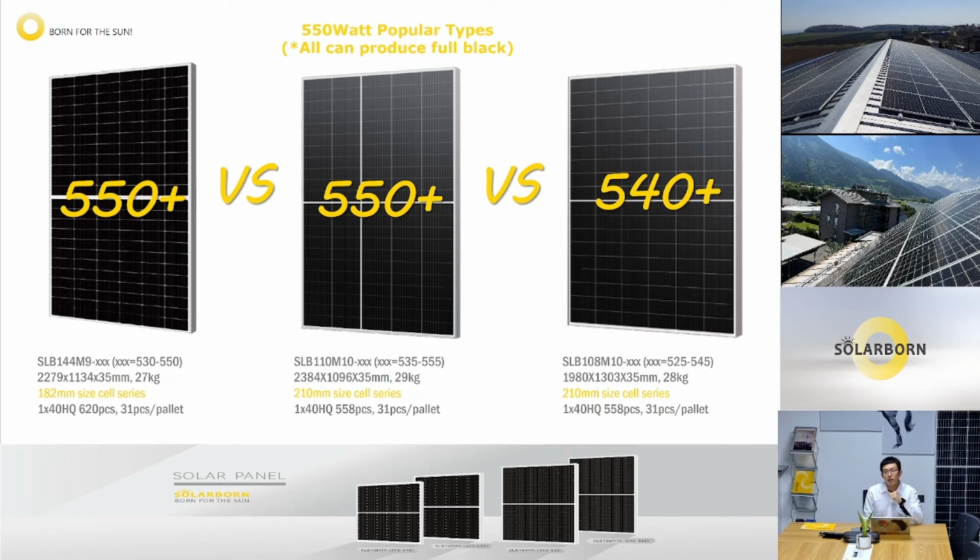The size of the solar panel is 2279 by 1134, with a 35 millimeter frame. And for the other two types, we make the panels with different numbers of half-cut cells, but the loading quantity is the same. So that's why for 550 watt, what you get from us is the first type on the left. It's a very popular and hot type.